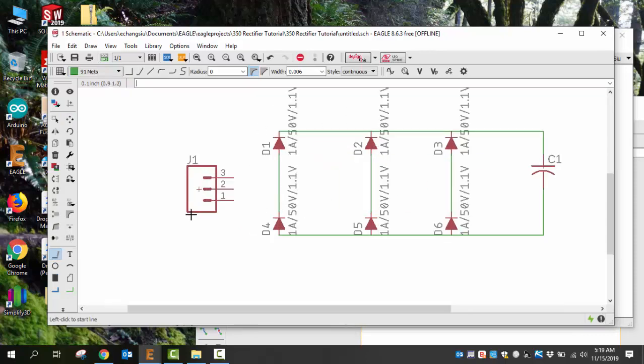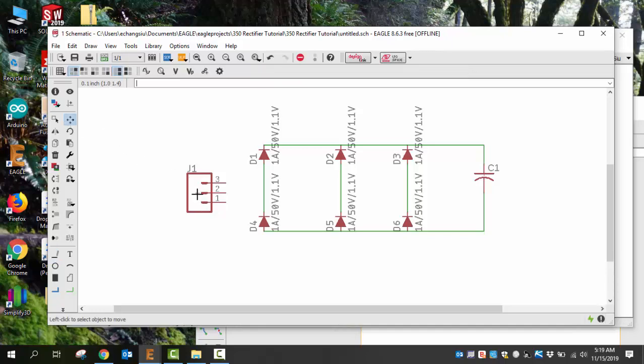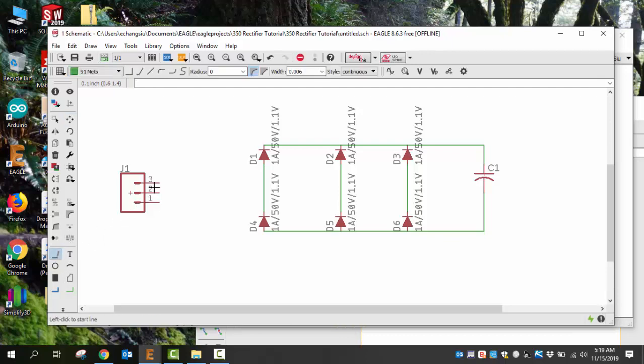So one thing I could do is use a trick, and this is something I do if I have a lot of wires. I'll click the tool and just make a little tail of wire. So I hit escape and make a tail of wire, hit escape, tail of wire, and hit escape. And then I come over here and I want to add a label.